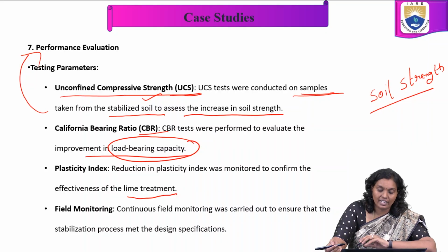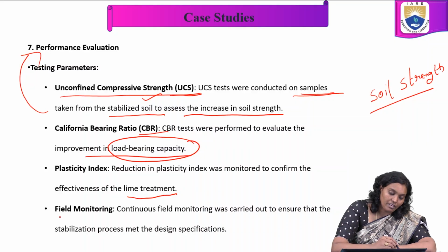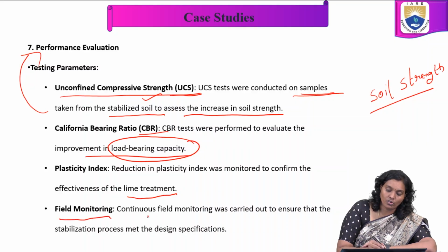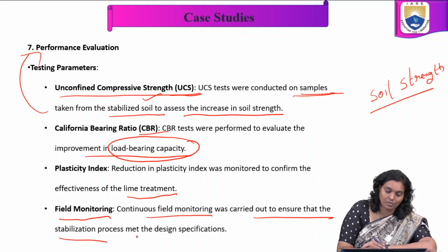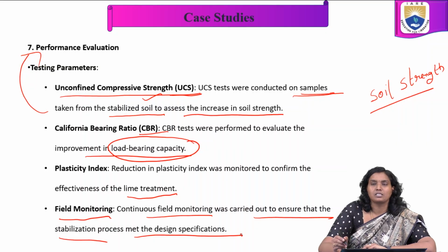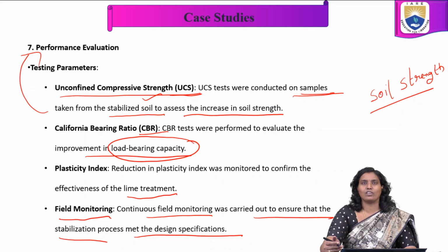So in this, the reduction in plasticity index was monitored to confirm the effectiveness of the lime treatment. In field monitoring, continuous field monitoring was carried out to ensure that the stabilization process met the design specifications. These are the performance evaluation.